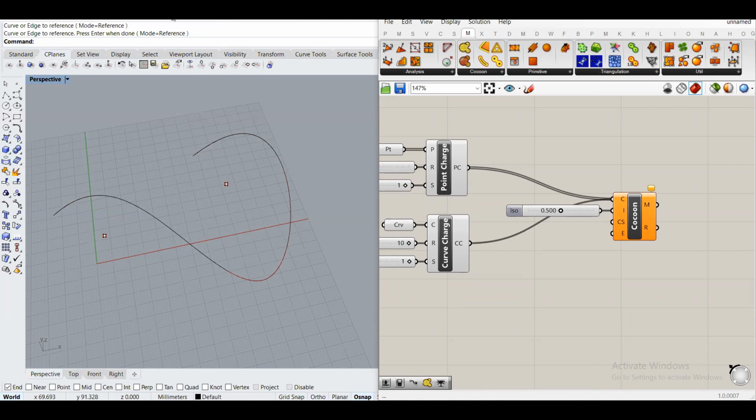So in here, everything is going to be divided up into cubes, into small cubes, right? Which you won't be able to see, but all of the building of the mesh is going to be happening inside of those cubes. The smaller the cubes, the smaller the voxels, the higher the resolution is going to be, but at the same time, the slower it's going to be, and so on. So you kind of need the balance.